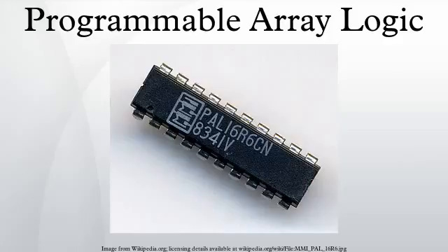However, they initially had severe manufacturing yield problems and had to sell the devices for over $50. This threatened the viability of the PAL as a commercial product and they were forced to license the product line to National Semiconductor. PALs were later second-sourced by Texas Instruments and Advanced Micro Devices. Process technologies: early PALs were 20-pin DIP components fabricated in silicon using bipolar transistor technology with one-time programmable titanium tungsten programming fuses. Later devices were manufactured by Cypress, Lattice Semiconductor and Advanced Micro Devices using CMOS technology. The original 20 and 24-pin PALs were denoted by MMI as medium-scale integration devices.